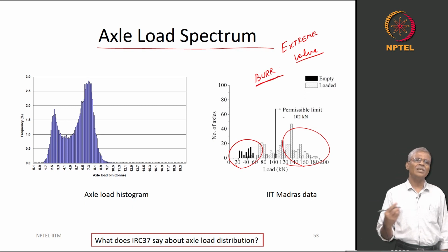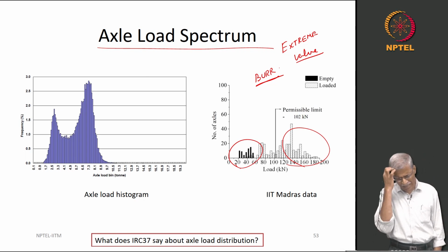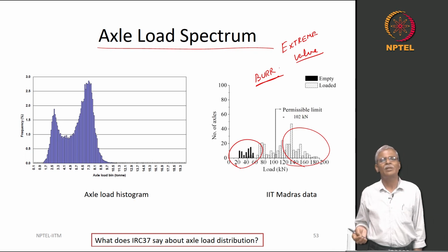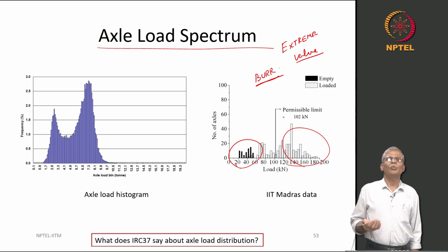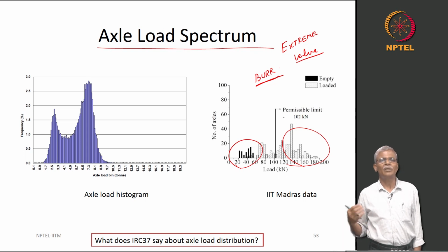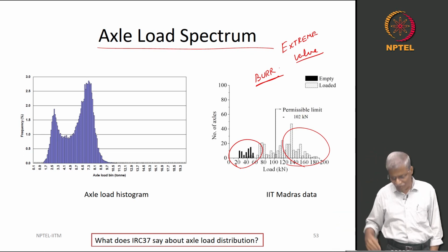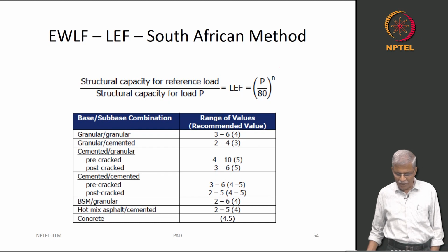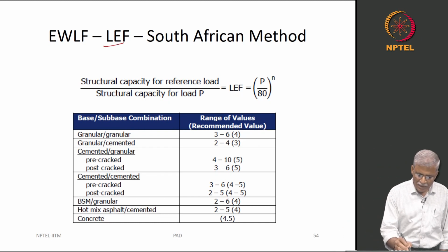These kinds of distributions and analysis will give us a lot of insight into how to analyze the axle load. It is not just a question of going to the site before designing a highway, collecting some 24/7 data and doing a volume count. We need to really understand the nature of the particular highway.